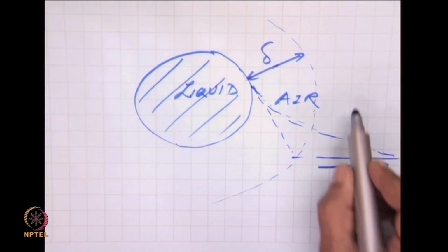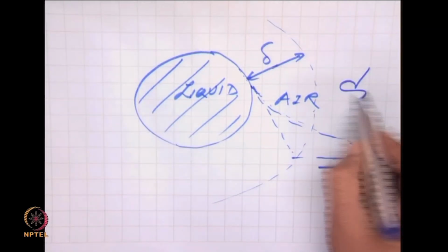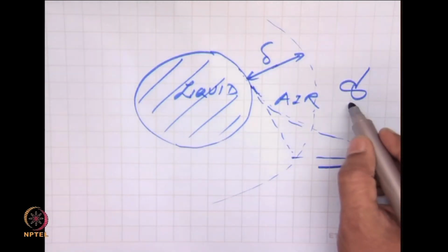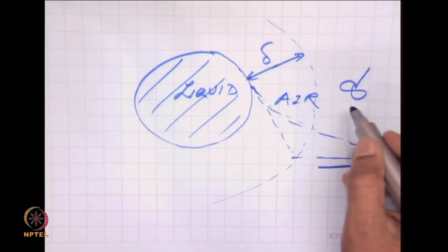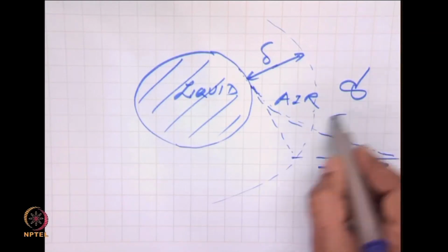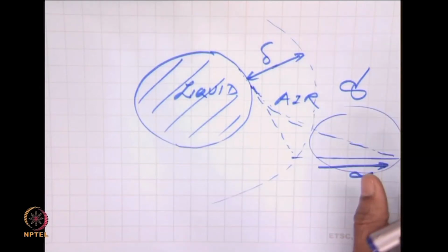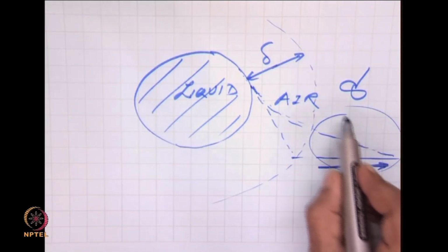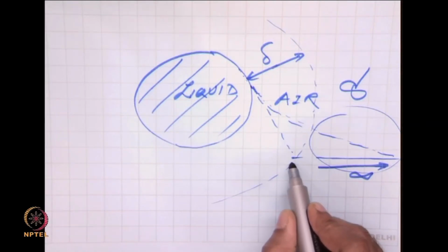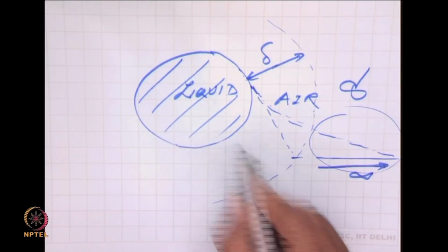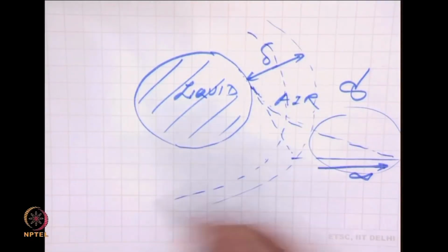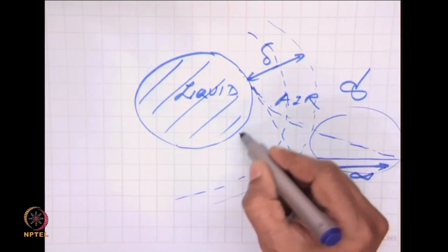If you for instance now replace the stagnant air by air which is stirred to have random or chaotic, turbulent motion, then what it means is that you will be able to destroy the concentration gradient in the bulk, and the concentration profile will become a uniform concentration profile now to a closer proximity to the drop. Our new film thickness will be lesser under turbulent conditions.